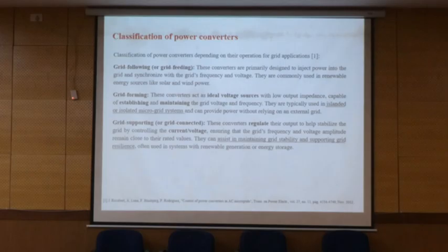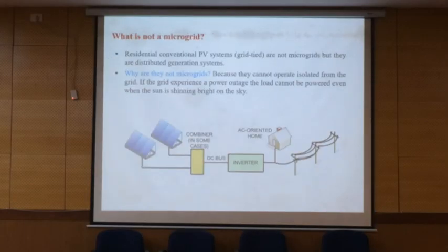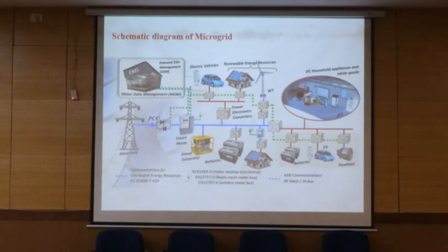Okay, so let me explain again one more time about the grid connected mode and isolated mode. So this is our microgrid. A microgrid is a part of the grid which can disconnect from the grid when we have some problem, and then we can return back to connected mode when the problem is solved. If you look here, we have this static switch.